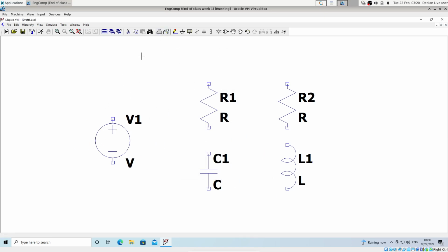Okay, I'm going to draw some lines to actually connect up the terminals of these different elements. So we use the wire tool from the toolbar here. I generally tend to click every time I get to a corner to pin down the wire. It will try to intelligently turn the corners with you, but I personally find it's more reliable to just click every time you want to turn a corner with your wire.